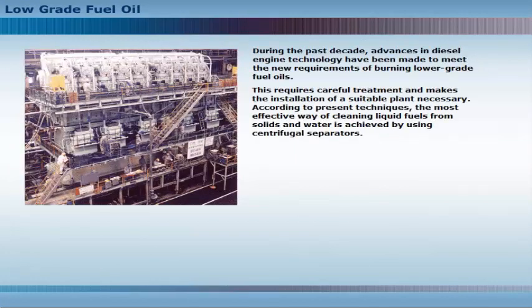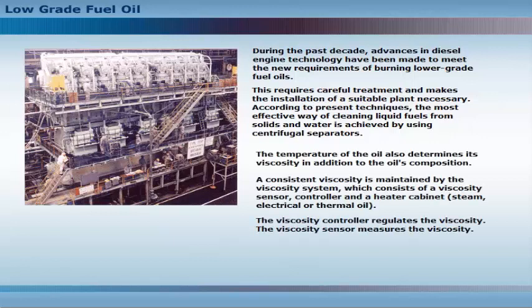During the past decade, advances in diesel engine technology have been made to meet the new requirements of burning lower-grade fuel oils. This requires careful treatment and makes the installation of a suitable plant necessary. According to present techniques, the most effective way of cleaning liquid fuels from solids and water is achieved by using centrifugal separators. The temperature of the oil also determines its viscosity in addition to the oil's composition.